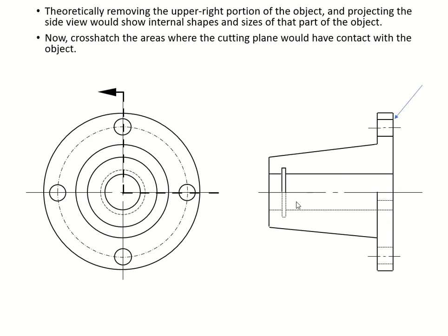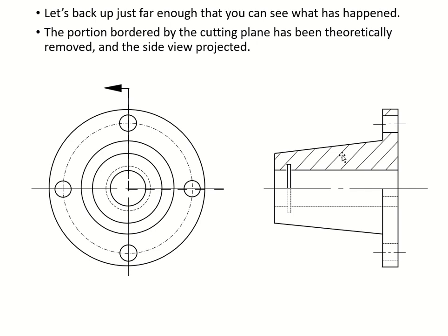We don't need to go the entire full cut because of the symmetry. Look at that, on this right side, this is your axis center line, which is this guy right there, and it's completely symmetric to each other, so therefore we don't need to draw both of them. Half section is enough, right? And then of course you will cross hatch your exposed area, which is inside of this cut plane.